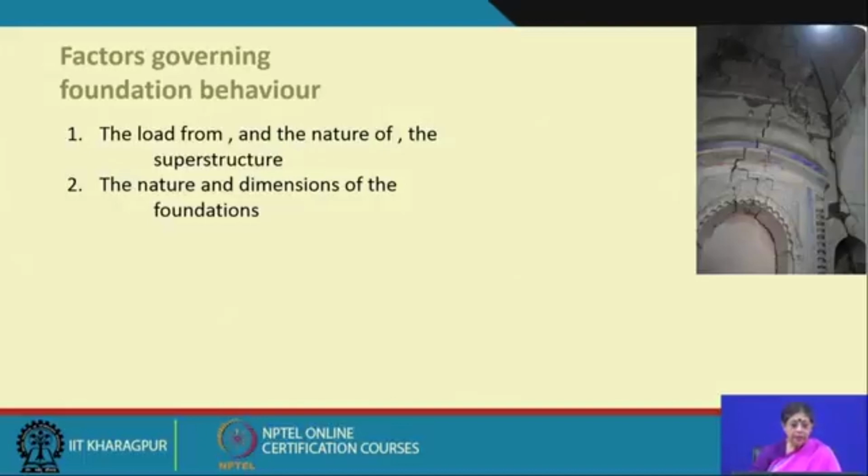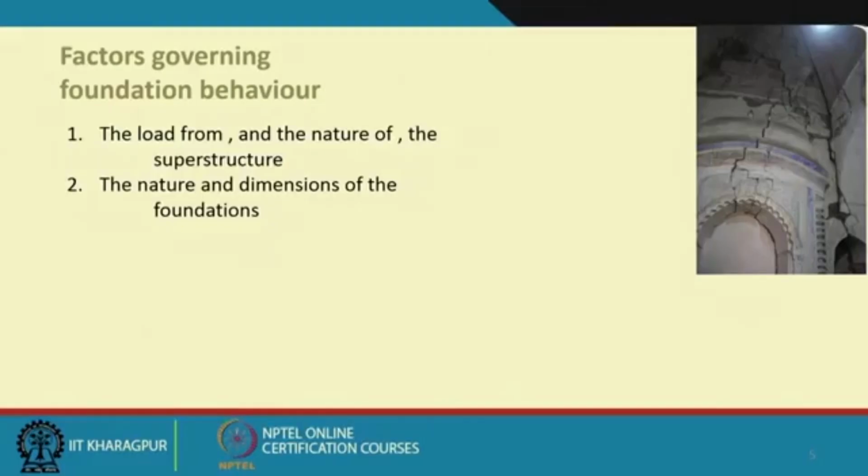The second is the nature and dimensions of the foundation. Sometimes in a historic structure, initially it was designed as a small structure with some sort of foundation, and then certain additional parts or additional floors were built on it. So, the nature and dimension of the foundation is not able to withstand that, and this is also a very important aspect.